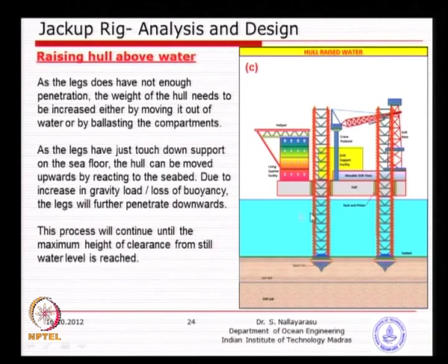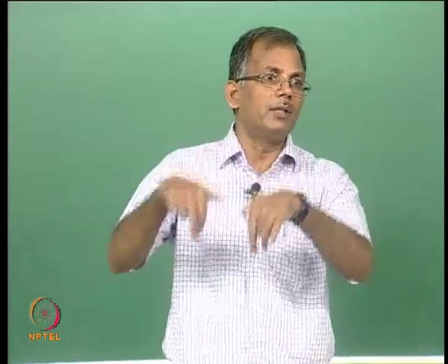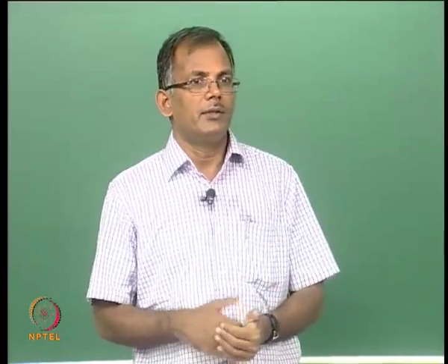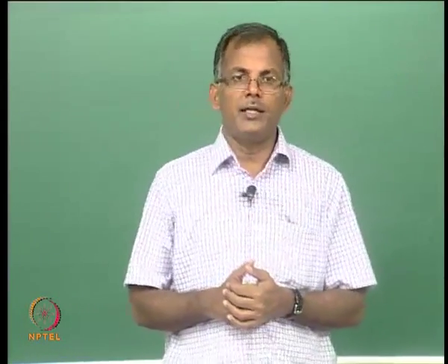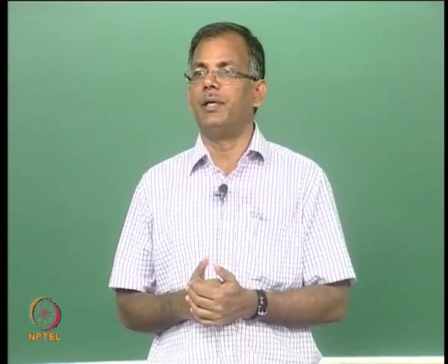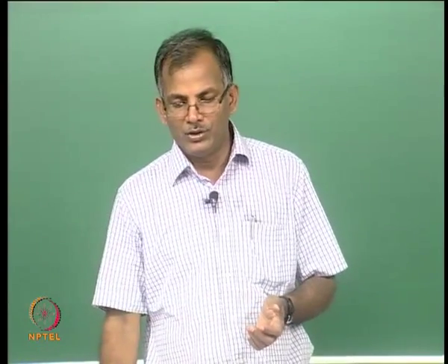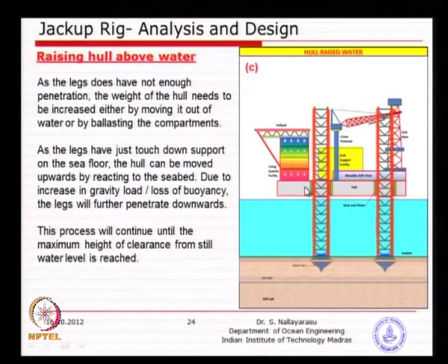Raising the hull above water, basically just to create additional weight, is again the opposite operation, but this is not going to be the kind of thing that I have drawn here, because it is going to be interactive. As soon as you increase the weight by moving up, the legs are also going to be penetrating. So, it is actually a slightly more complex operation than just step by step. It is not that the leg is going to stay at the surface when you are moving upwards and then you are going to do this filling.